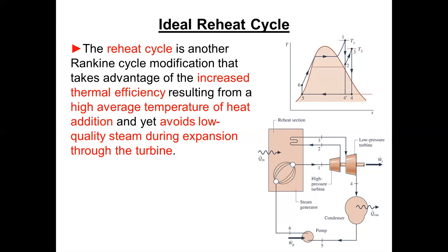So then when we come out of the boiler, we go initially into the high pressure turbine. We expand. As the pressure drops, steam expands, turns the shaft, puts power in, gets electricity out, and then we get down to a point and we come back out of the turbine. Ideally this is at constant pressure, but in reality we'll have a 30, 40, 50 pound drop through here. But we go back to the boiler.